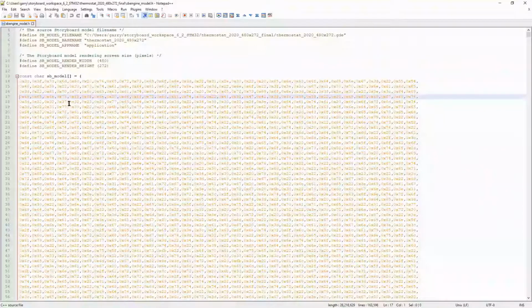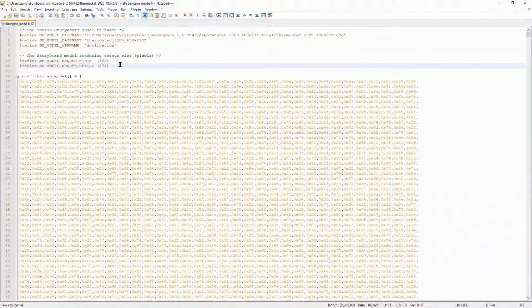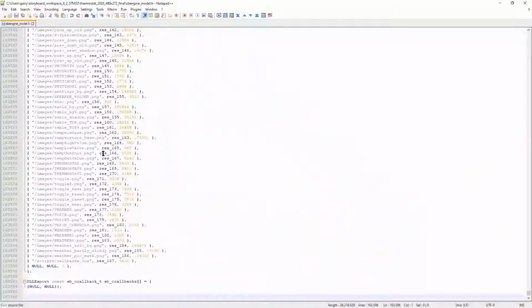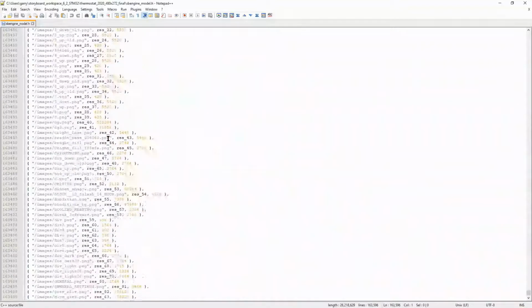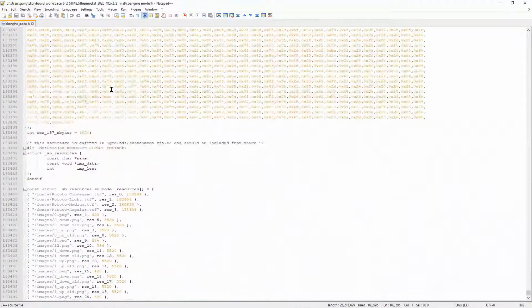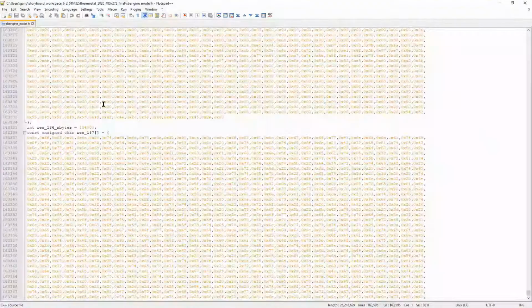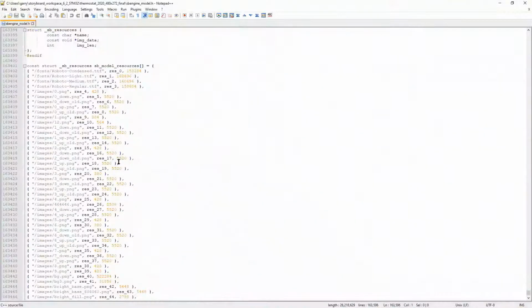You can see here that here's the Storyboard model, and we've created a metadata and added that to the top, which is useful for revision control. And if I go to the very end, you can see here this is a virtual file system layout. This is the way that we're representing those resources in our header file as blobs. And you can see here's one of these resources represented as a character array. And so the virtual file system is very interesting. It's very lightweight and very straightforward. It means that you don't have to run a full file system on your microcontroller.